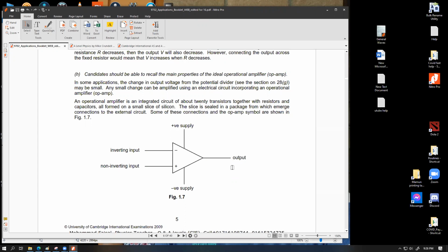That will be 0. From 0 to 0.1, you have 0.1 magnitude, and from 0 to 2, you have a magnitude of 2. So for the op-amp to work, one of the ends has to be fed to give it a sense of ground, that this is my lower limit. Whatever the other input differs from that ground value, I will amplify that amount.